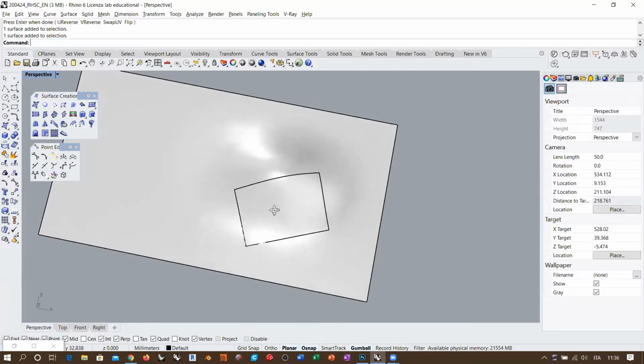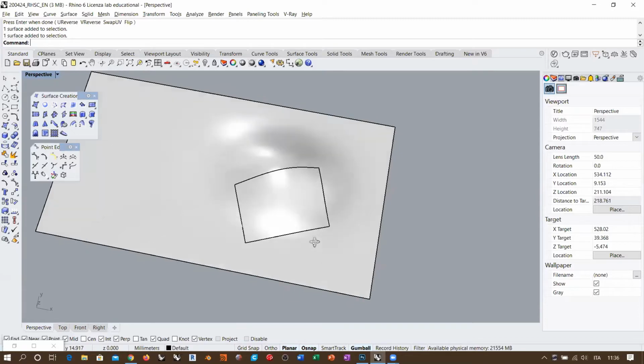But if you take a look at this, the white reflection here suddenly interrupts at this edge. So visually, this is already telling me that there is not enough continuity along this edge. And also along this edge, there is this displacement between this reflection in this area and this reflection here.